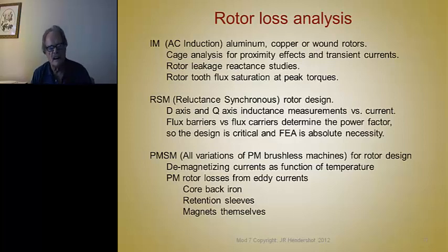And then the losses, as we've already said, we can estimate what the rotor losses are, and it's much easier to estimate the iron losses in a stator than it is a rotor. It's much tougher in the rotor because of the motion of the flux and the concentrations of where the flux densities are, and the motion of the dφ/dt in the rotor as the rotor rotates